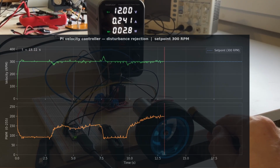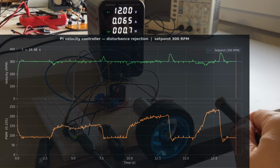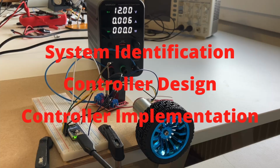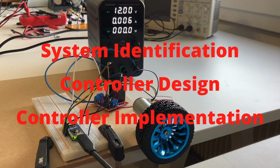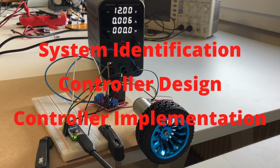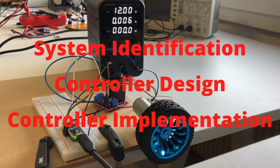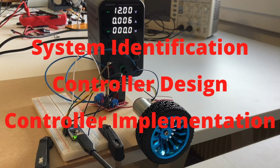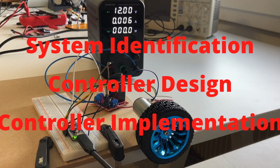The speed barely moves. In most hobby projects, the default is to tune by feel. If instead you first identify the plant, the system being controlled, here the motor, you can derive the gains in 3 lines of algebra. The pipeline: measure the plant, fit a model, design analytically, discretize, flash.